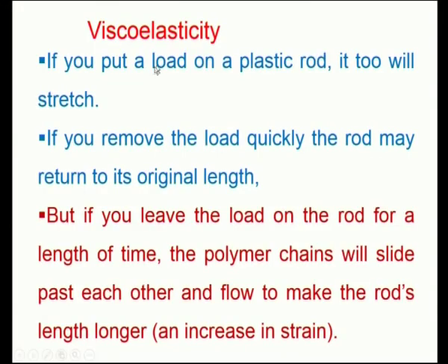If you put a similar load on a plastic rod, it too will stretch. Now, if you remove the load quickly, the rod may return to its original length. But if you leave the load on the rod for an extended period of time, the polymer chains will slide past each other because of the application of the force and may try to flow to make the rod longer.